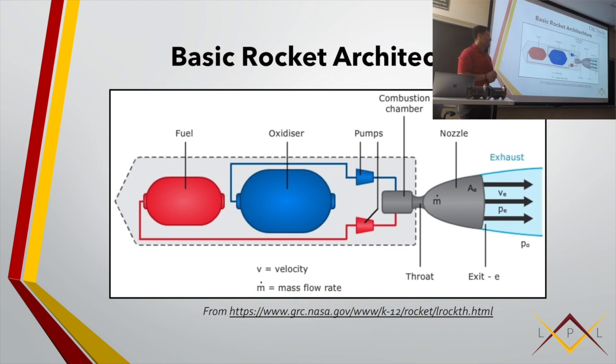So the way that all launch vehicles work is that they have these running at as low a pressure as they can, and then they'll use turbo pumps to pressurize it, and therefore none of this needs to be rated for high pressure. Even though the pumps may weigh something, it's a lot more mass saving than having thick tanks. So that's pretty much a general setup.